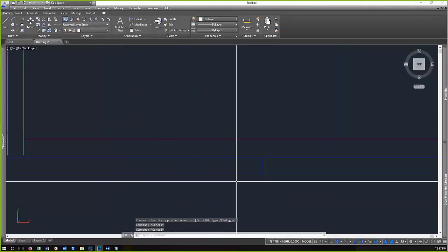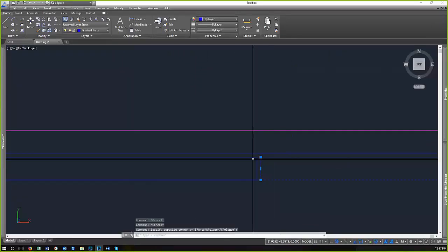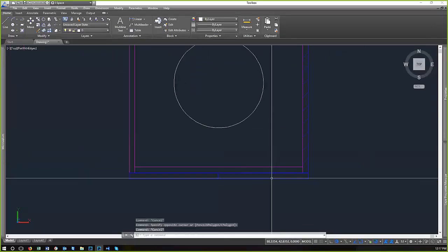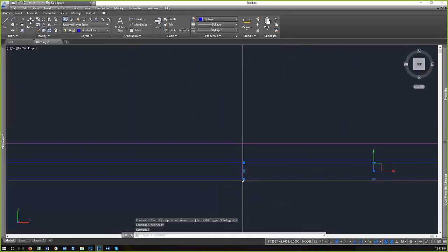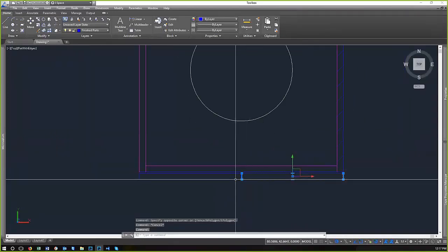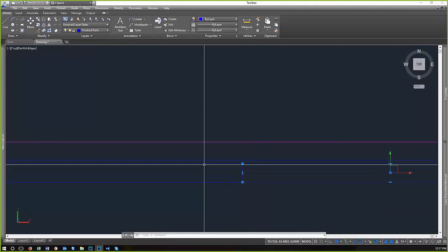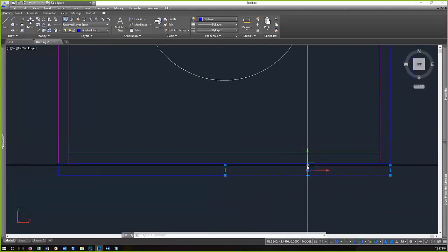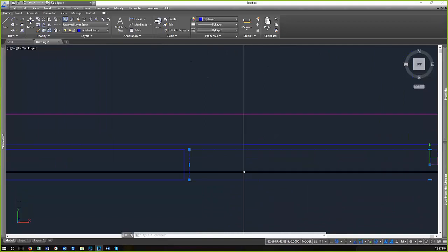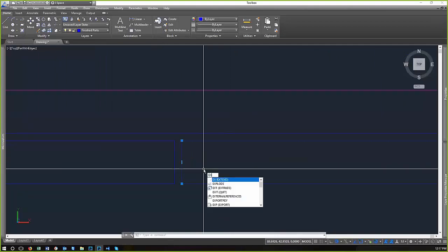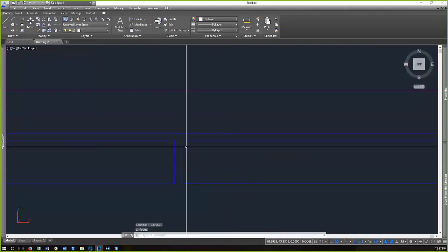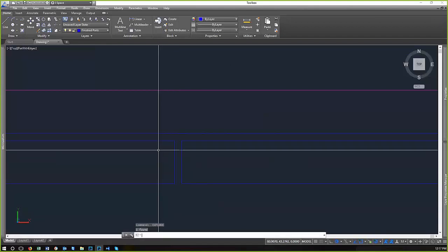So if, let's do the backside of the doors. These doors are rectangles. So in order to turn them into lines so that we can modify the properties individually, what we'd have to do is explode them. So that turns a rectangle with all of its properties into lines. So explode, it's a modified command that we're going to get into a little bit later. But we'll do that to both doors.